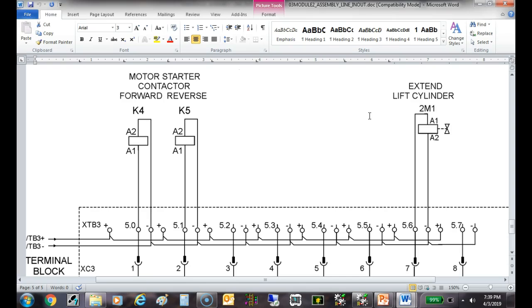So you can see why you would kind of get confused here, because this is not a relay, this is a solenoid, even though they operate basically the same, right? You understand? They're both coils of wire, but one of them moves an actuator. The other one controls contacts. So this one right here should have that slash line through it. So Gert, when he drew this one, he didn't draw it quite right.